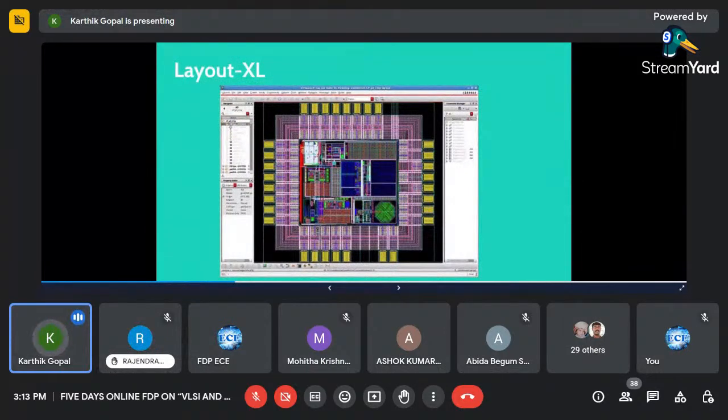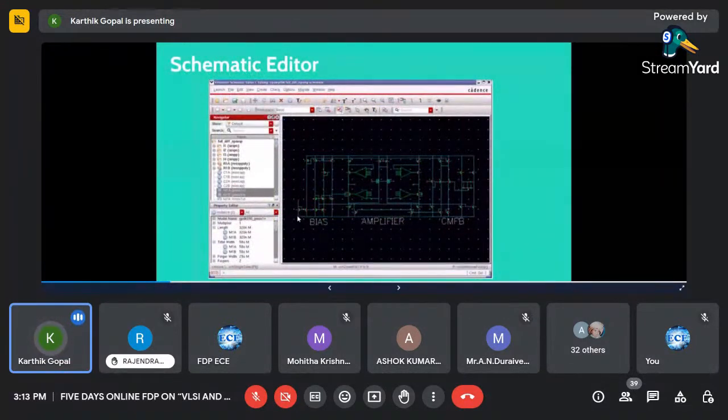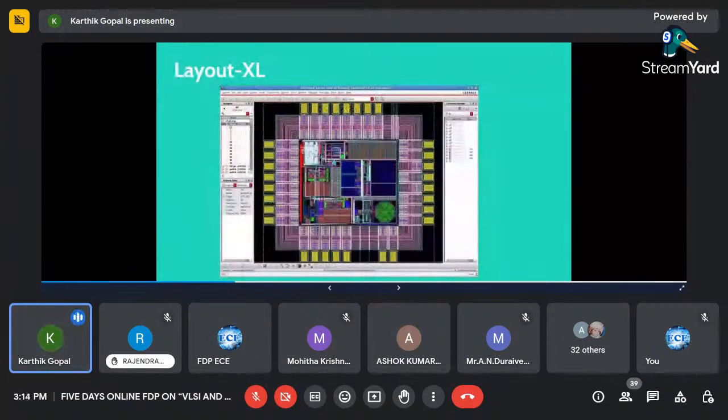So that requires a connection between the schematic and the layout, so that it implements all the MOSFETs and the resistor, capacitor, all the devices. So connections, it will show you the connections from the schematic. For example, in this picture, on the left side you have one MOSFET, left bottom, and the gates of the two MOSFETs are connected. So that connection will be directed to the layout. It will tell you this device gate has to be connected to that device. So that we will check by the LVS, the layout versus schematic tool. So that will check all the cross connections.